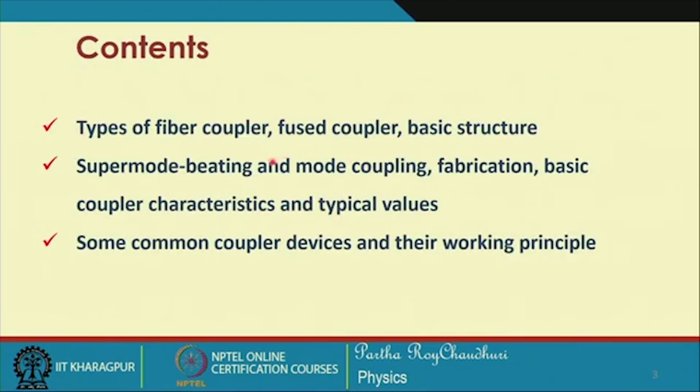There is a large variety of fiber couplers and components existing. So, we will initiate the discussion with the fiber coupler, fused coupler, basic structure, then supermode beating, that is the mechanism by which this coupling takes place, fabrication of fiber coupler, some basic coupler characteristics and typical numbers associated with these fiber couplers, and some common coupler devices and their working principle.